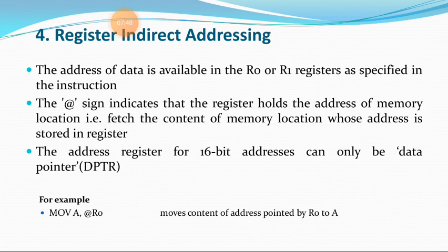Here, also known as register indirect addressing or indirect addressing mode. In this addressing mode, the 8-bit address of the operand is stored in a register, and that register is specified in the instruction. The registers are R0 and R1 of the selected bank of registers, or we can use the stack pointer as an address register for storing this 8-bit address. So normally we are using the